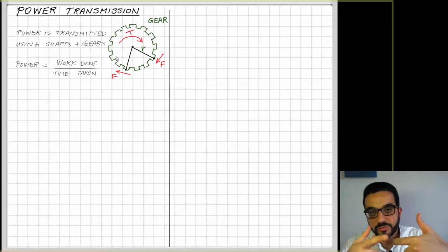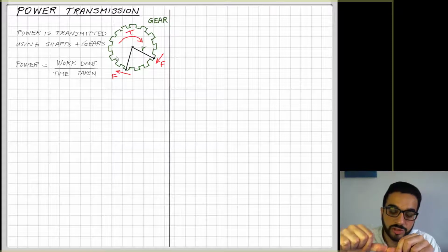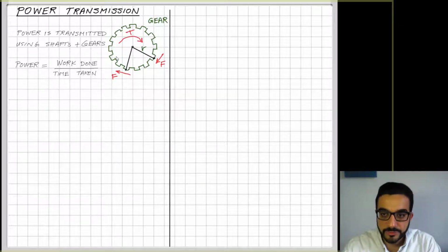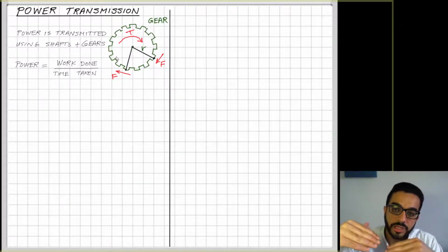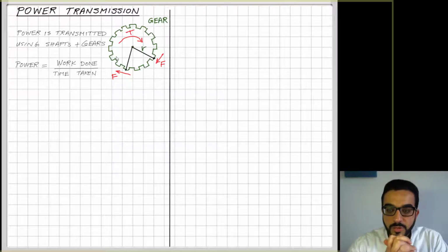So with this interaction between the two gears, or the tooth of each gear together, there's a force pushing. Each tooth is pushing the other one. That force is kind of the translation of the torque from one shaft to the other shaft through the gears. So we're representing that force as F. This F is the force on the tooth, and with the rotation of the gear and the shaft attached to it, the force kind of rotates, or that interaction of the tooth rotates until this tooth departs. So we're looking at that rotation.